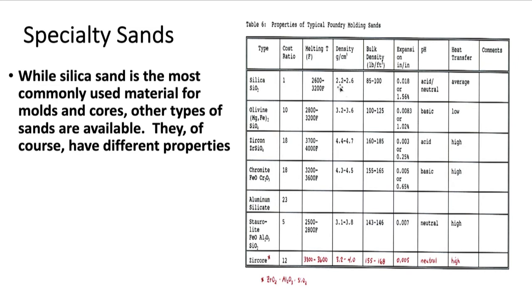If you take the density of a big block of silica, it will have this density, but the bulk density asks, well, if I have a cubic foot, how much is that going to weigh? And this can change with the binder content and stuff like that as well. But generally, you usually say silica is about 100 pounds per cubic foot. So it's an easy way to estimate the weight of some amount of sand.